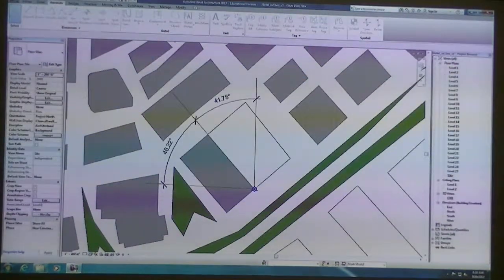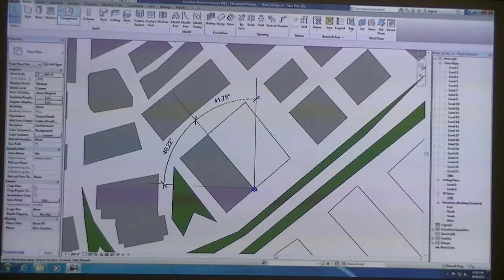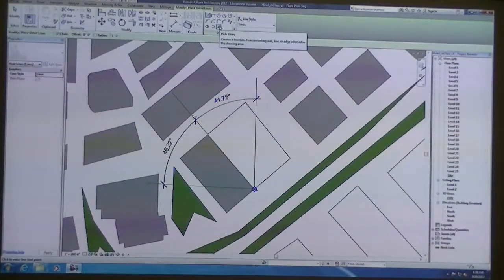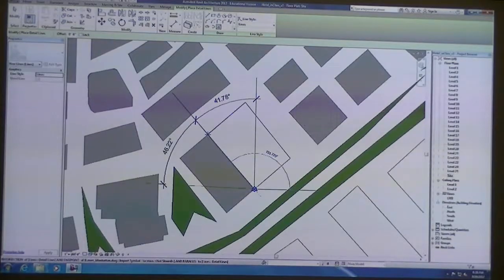What did you pick this line here in the center to get it to extend out there? Yeah, so on the angle, I went into Annotate, used the detail lines, then Pick Lines, and selected that. While it's selected, there's a little drag handle, and all I did was drag that out and keep it locked in position.